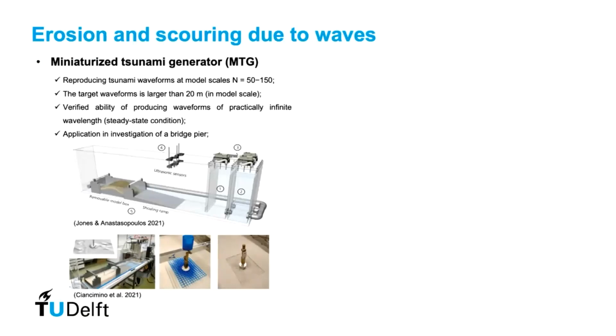This container has two separate chambers, and you can build a structure, for example, here drawn as an embankment, and discharge a wave or a sudden release of water with a given height and explore what is the effect of the impact of that wave over the embankment. And by doing that and getting right the stresses on the model, you are able to tell if that critical infrastructure will sustain the action of those stresses.